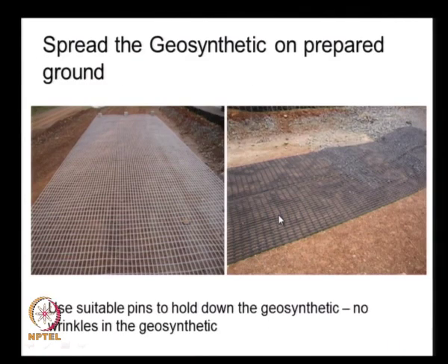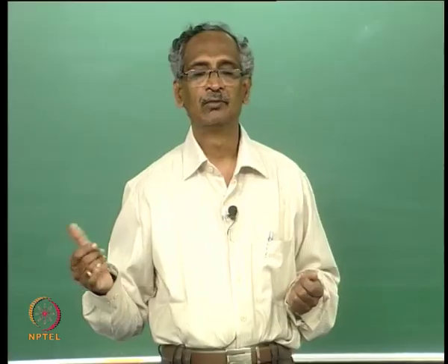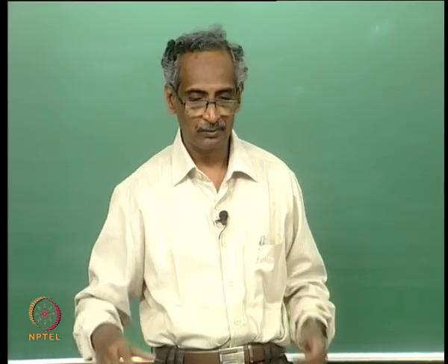and level the ground, and then on the prepared ground we stretch the geogrid or geotextile, and we should pin them down, because sometimes these geogrids may be so stiff that they have a memory, they just simply roll back. In that case we need to pin them down.